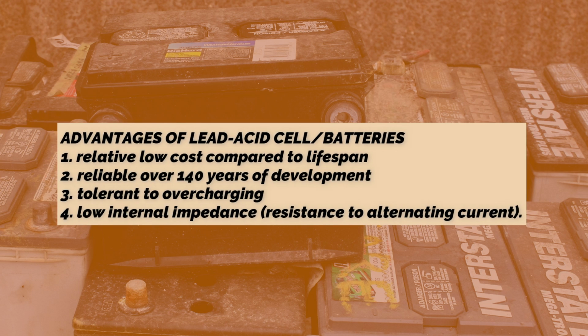The advantages of lead-acid cells or batteries: 1. Relatively low cost compared to lifespan. 2. Reliable over 140 years of development. 3. Tolerant to overcharging. 4. Low internal impedance or resistance to alternating current.